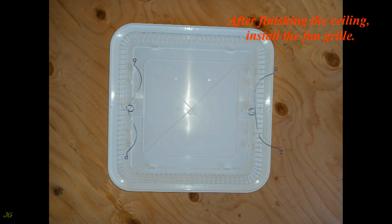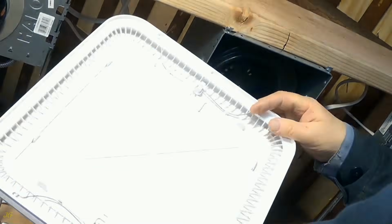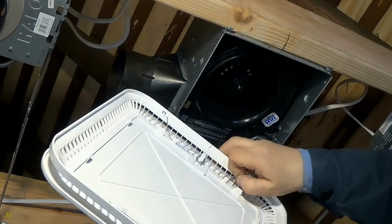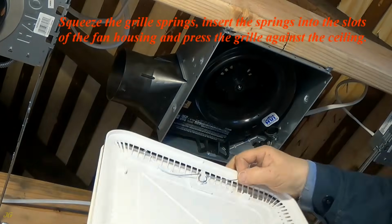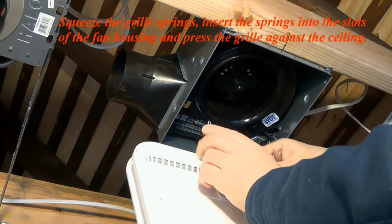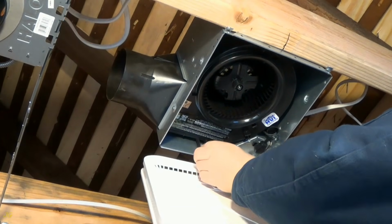After finishing the ceiling, install the fan grill. Squeeze the grill springs. Insert the springs into the slots of the fan housing and press the grill against the ceiling.